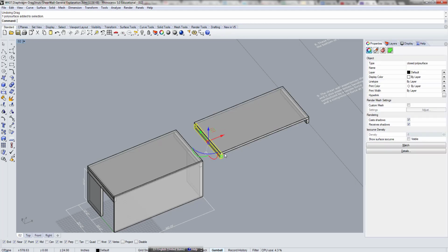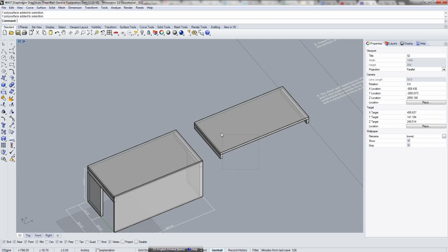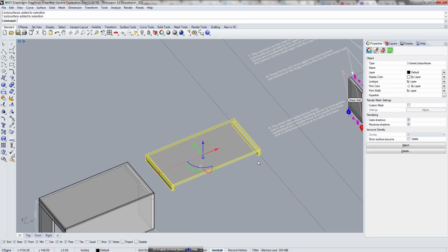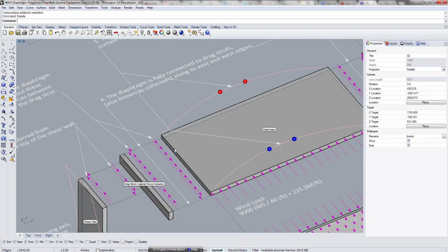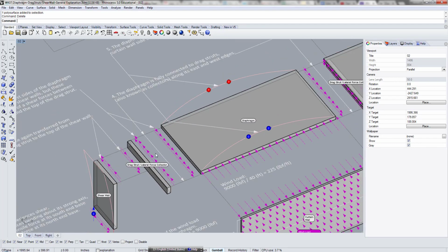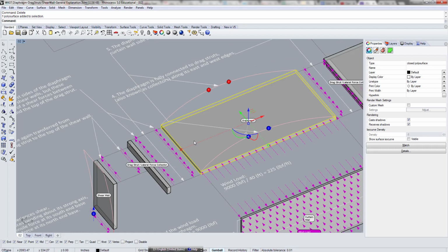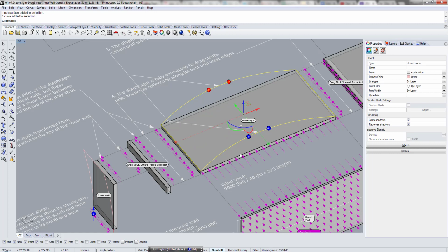But it's fully attached to this beam. So for the entire length of this beam, it would experience this force, which is trying to push this way. This diaphragm, which behaves like a beam, tries to deflect like this, right? But it's constrained at the edge, so it's going to try to push this collector or drag strut this way, for the entire length of the thing, right?